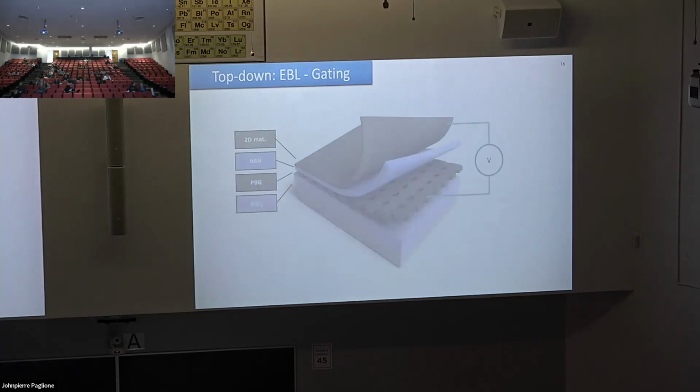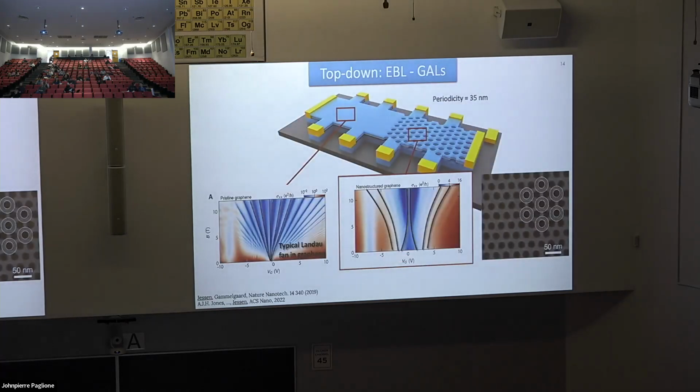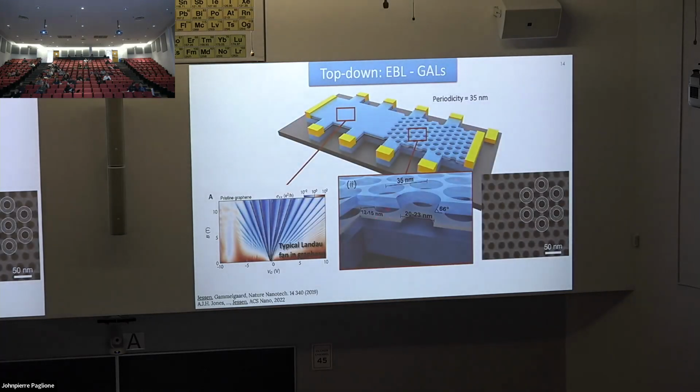Yeah, that's right. So in this situation, what we started out with was a resist sitting on top of this top blue layer. Then we used the E-beam to open up holes in that resist, and then we etched into first the boron nitride and then the graphene. It was kind of a multi-step etching to get down to the graphene. That also helps us because all of the polymer residues and all of this weird stuff that might be left behind is sitting on top of the boron nitride, so not touching graphene. And that helps a lot with quality issues.